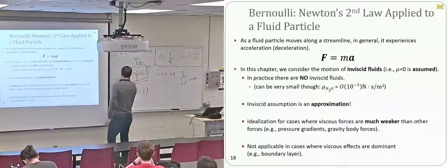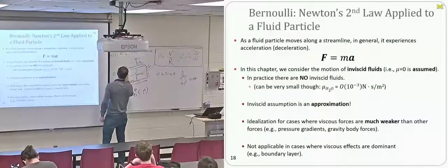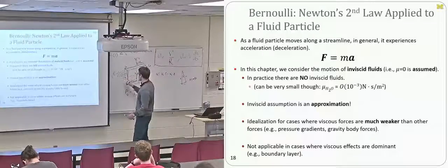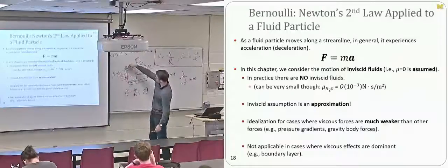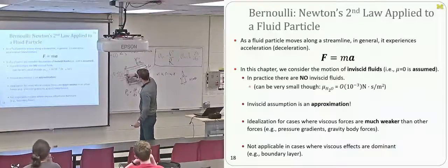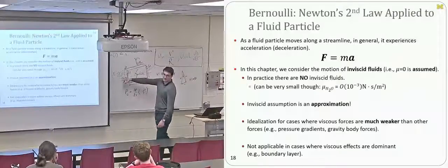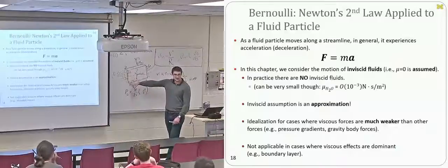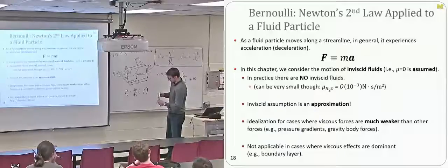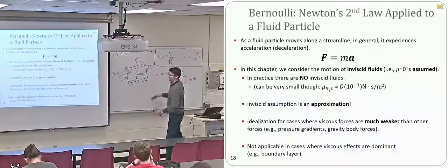So over here, we've got P naught minus dP ds times ds over 2, and then this whole thing needs to be multiplied by an area, which is going to be delta y by delta n, right? This is times delta y, delta n. So this is the pressure force acting on this face of our little fluid volume. All right, this face. Someone should have an easy time now with the pressure Taylor series on this face.